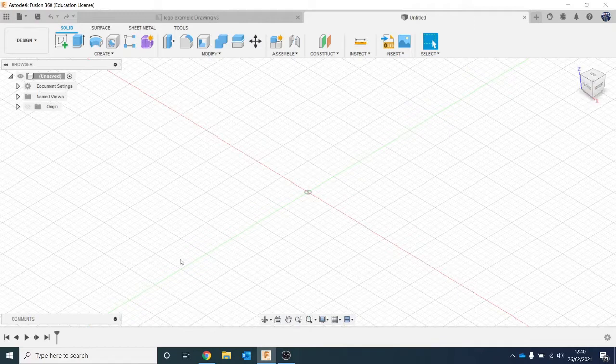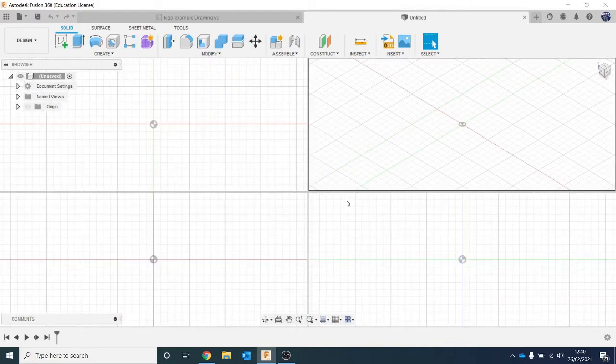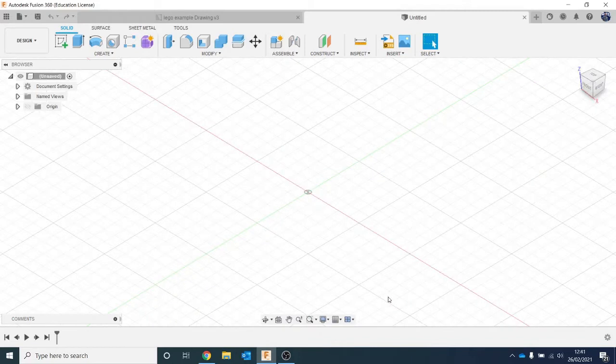Then on the screen itself, as you see at the minute, the standard that I've got is loads of grid lines on there. You can edit that if you want to. So down at the bottom, you will find these options here. So you've got viewpoints. That means I can basically have a look around. What this is doing now is showing isometric top, side and bottom. I don't want to have that on, so I'm going to turn that off. So let's go to single view so I can go back to my original view.